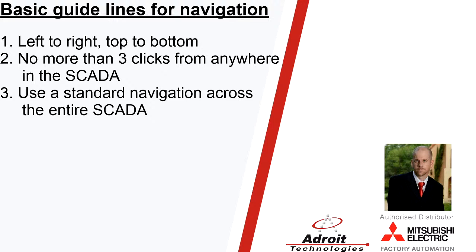And then another important one is a standard navigation across your entire SCADA package. So again, this comes down to our standards. I know that for those of you that have been following this little series, you know that I keep referring to a document called the FDS, or Functional Design Spec. And that's typically what I would start off with, is I define a standard across the entire project so that